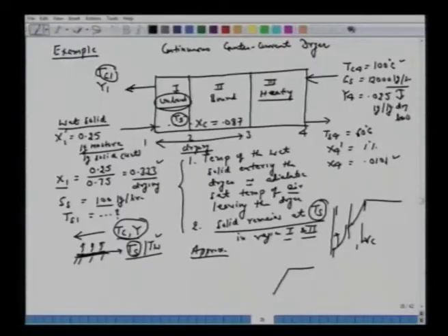You have to take the same solids and simulate in the lab, more or less with the same Reynolds number of the gas fluids, the same temperature or the solid surfaces to which it's exposed in the laboratory. So one has to establish this drying curve, which we have been using quite rigorously in the first lecture on this topic. All right. So in this problem, Xc is given as 0.087 kg of moisture per kg of dry solid, and it says that Xe, equilibrium, is approximately 0.